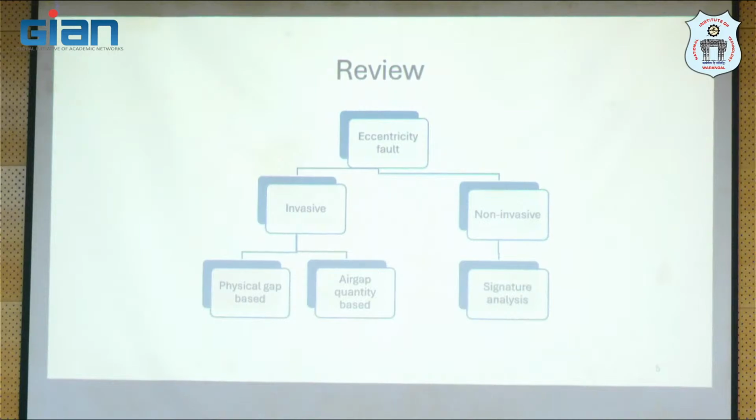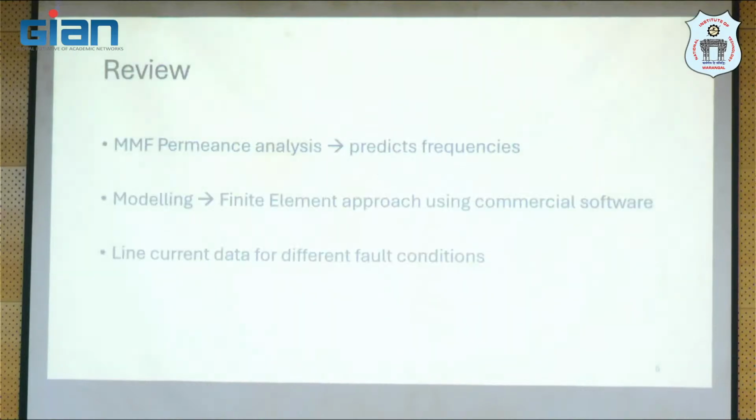One of the popular non-invasive schemes that I presented yesterday is motor current signature analysis. So in motor current signature analysis, we carry out what is known as a magnetomotive force permeance analysis to predict the harmonic frequencies that would appear in the line current spectrum.